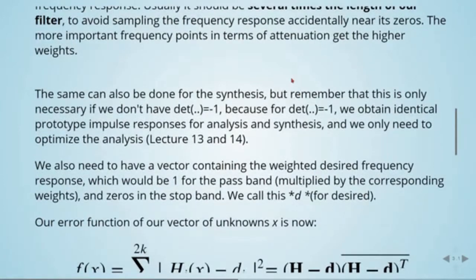The same can also be done for the synthesis, but remember that this is only necessary if we don't have the determinant equal to -1, because when we have the determinant equal to -1, we obtain identical prototype impulse responses for both the analysis and the synthesis, so we only need to optimize the analysis. Well, we've seen this in lectures 13 and 14.